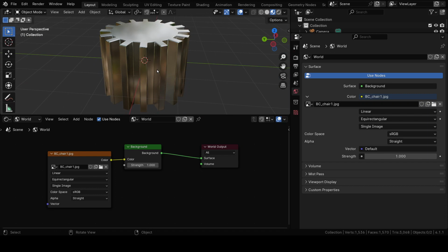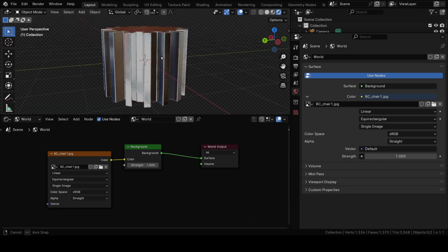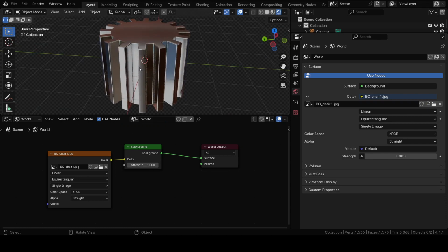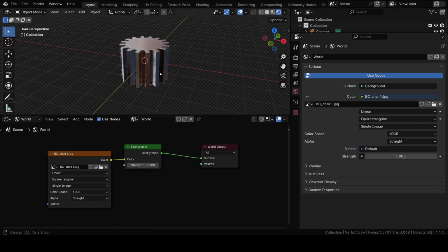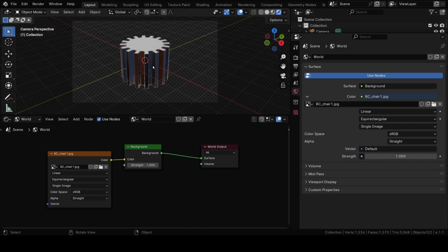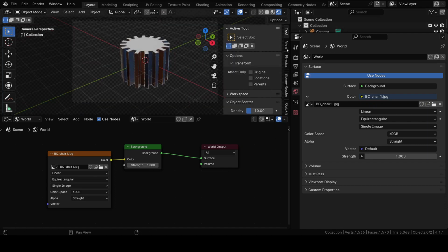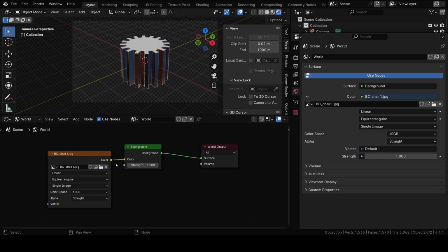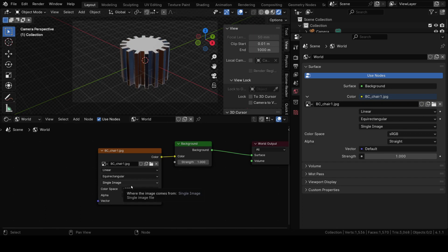By default Blender has that image. So I'm going to access that default, native image of Blender to bring the same kind of effect in the rendered mode also, so that I need not create any light. If I'm showing a camera turntable animation or something, I need not do any lighting. Just go to World and do the linking that I'm going to do. If you do that, that will be enough. You don't have to put any extra light.